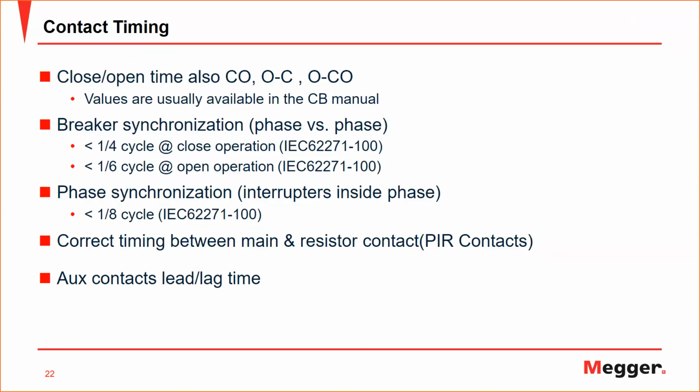And then we have the combination of both, an auto reclose and trip free, where you have a fault consistent that you open for the first time, and then the auto recloser close, and then the fault is still existing, you have to open again immediately. So these are the 4 timing tests or sequence that we're going to do.